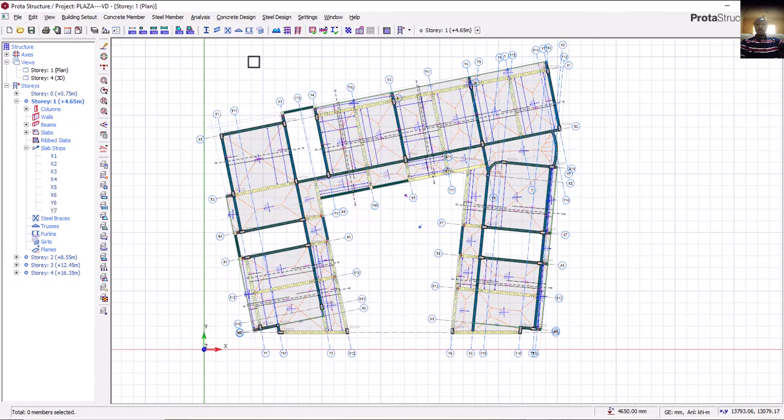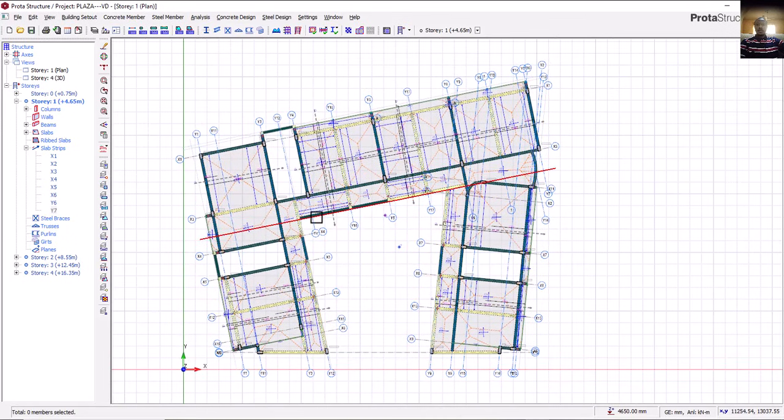And to confirm it further, you can come to this concrete design. First of all, let's look at slab analysis and design. Let's click on this. In this case, is it design? Is it check design? Do not modify existing one. Yes, because I already have my steel. I want to see if what I have on ground is okay.